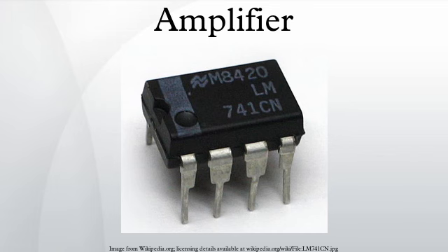Different methods of supplying power result in many different methods of bias. Bias is a technique by which the active devices are set up to operate in a particular region, or by which the DC component of the output signal is set to the midpoint between the maximum voltages available from the power supply. Most amplifiers use several devices at each stage. They are typically matched in specifications except for polarity. Matched inverted polarity devices are called complementary pairs.